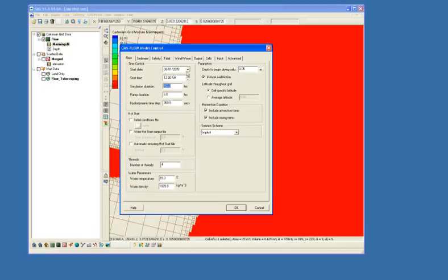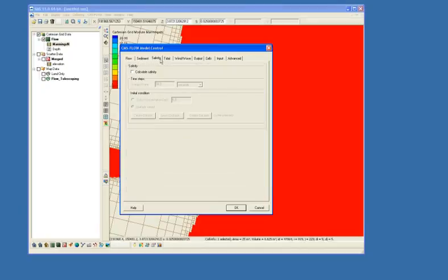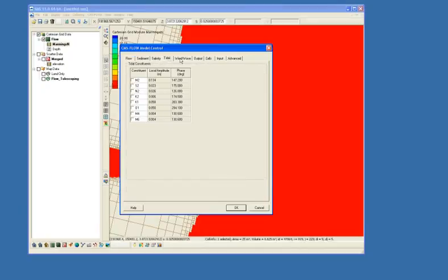So it makes it a little bit easier in this area. Also, we're going to be changing the start date and time block, because it writes it to the file in a strange way. But let's see what we got. We have 4 threads going to be used, 0.05 meter depth, wall friction, no salinity transport, no sediment transport.